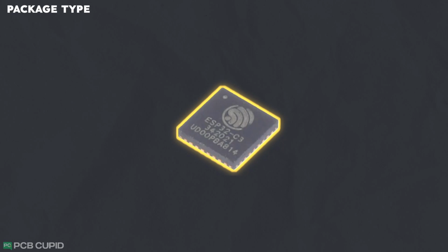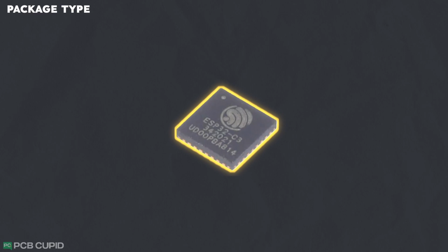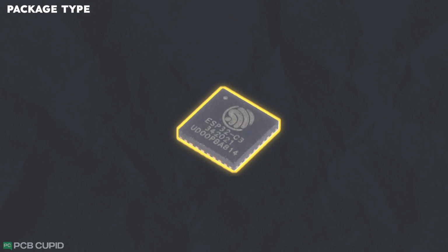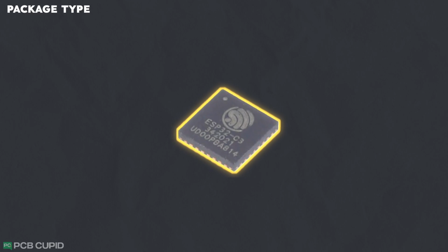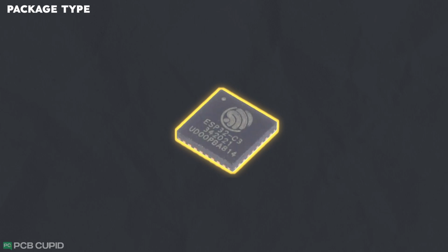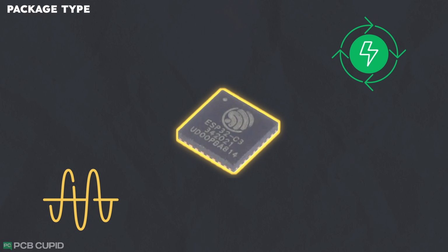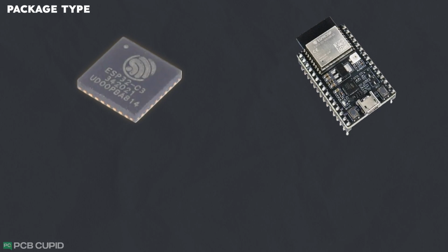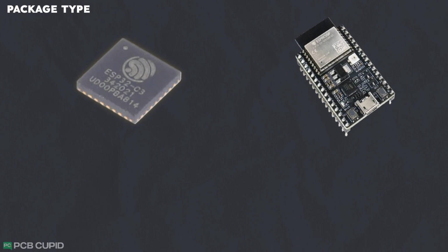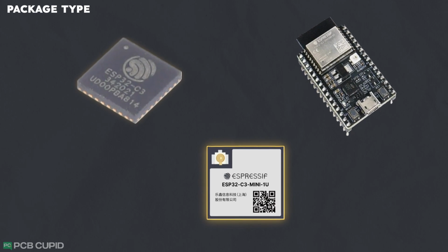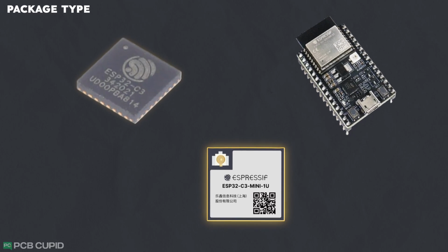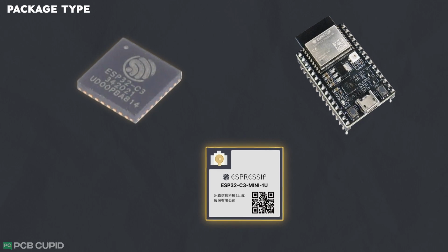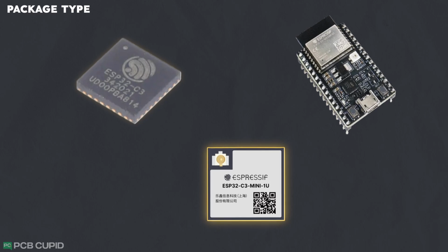Now, coming to the other extreme, the bare IC would help us make our PCB very small and efficient. It is also super easy to install using an SMT machine. But it would increase the complexity of the circuit, and we might need to worry about power conversion and the RF section of the microcontroller. So that's the reason I had to find something between these two variations and ended up choosing the ESP32C3 Mini. It not only satisfies all the requirements for the master node, it is also small and compact and also takes care of the power management circuit and RF section of the microcontroller.